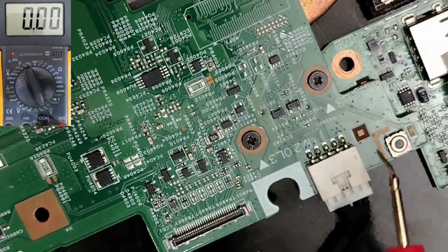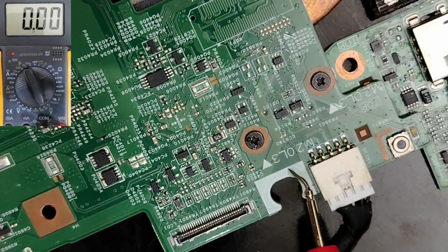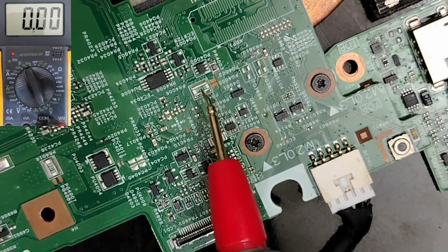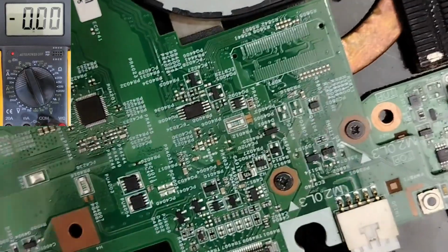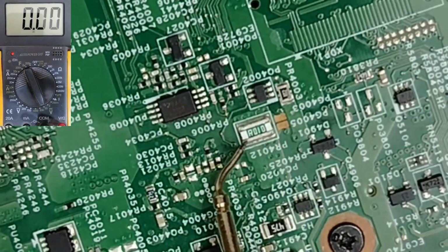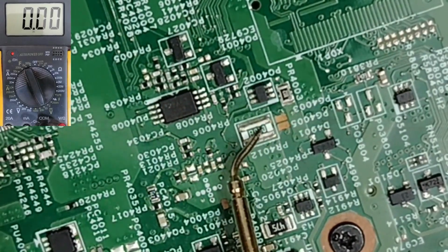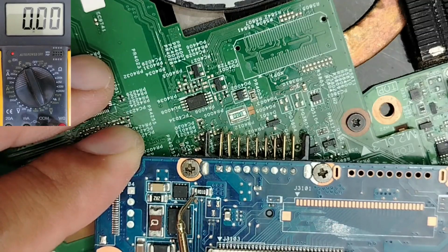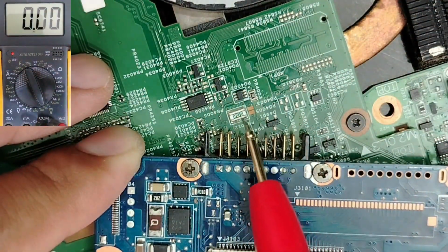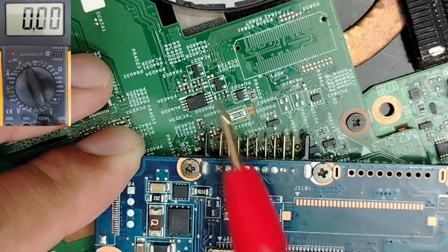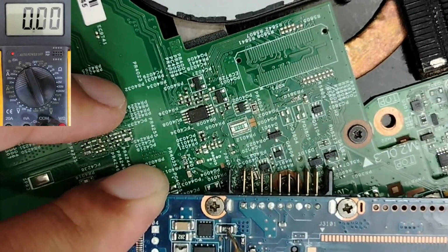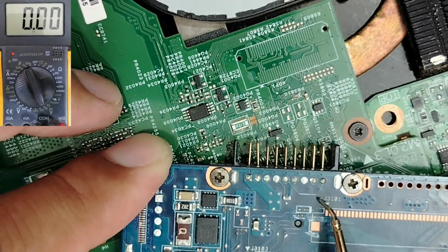So if there is a problem in the power jack, the board will be off, a dead board. If there is a problem here, for example, this one is bad, of course. How can we check? So for beginners, how can we check this kind of resistor, current sense resistors? Always you will find R010 for the majority, of course. For this board also, guys, here we have R010. Remember, always current sense resistor. Very important, because from this point, the B plus, the 19 volt, will be distributed to all circuits in the motherboard. If you have a problem with this current sense resistor, the motherboard will be dead.